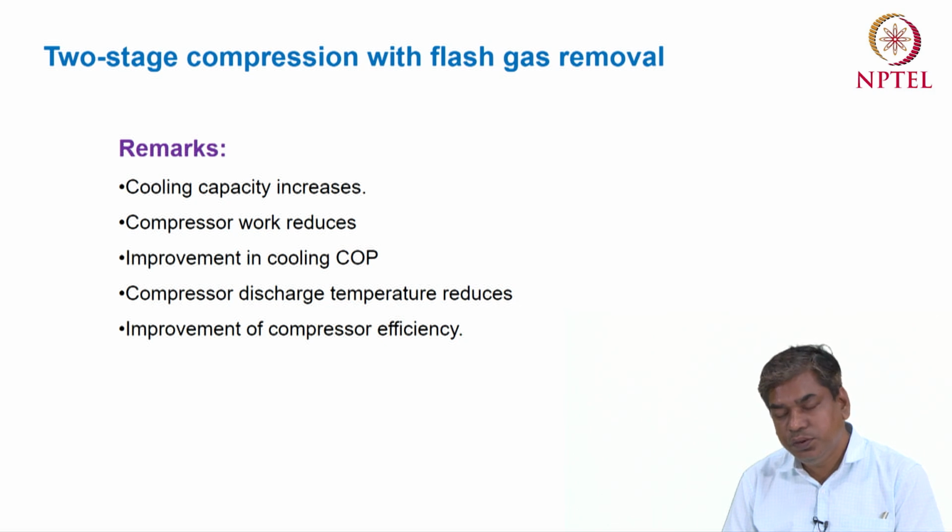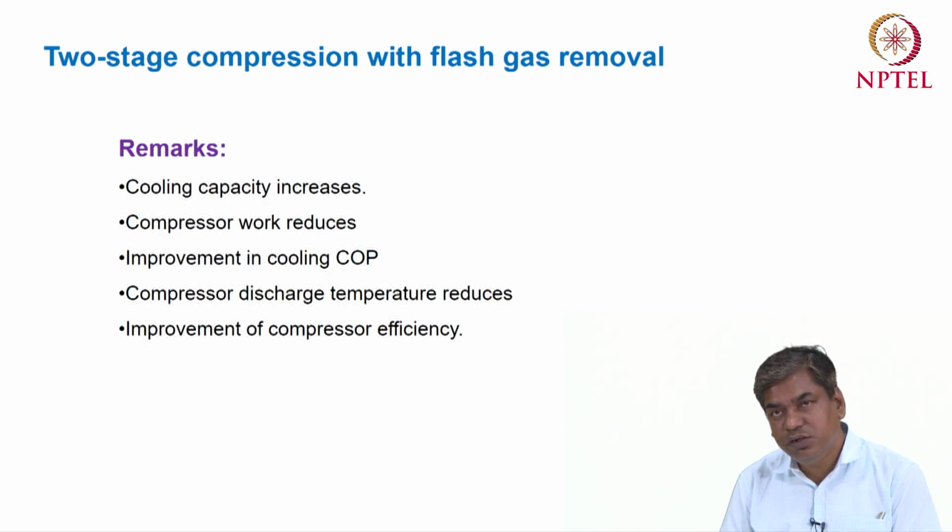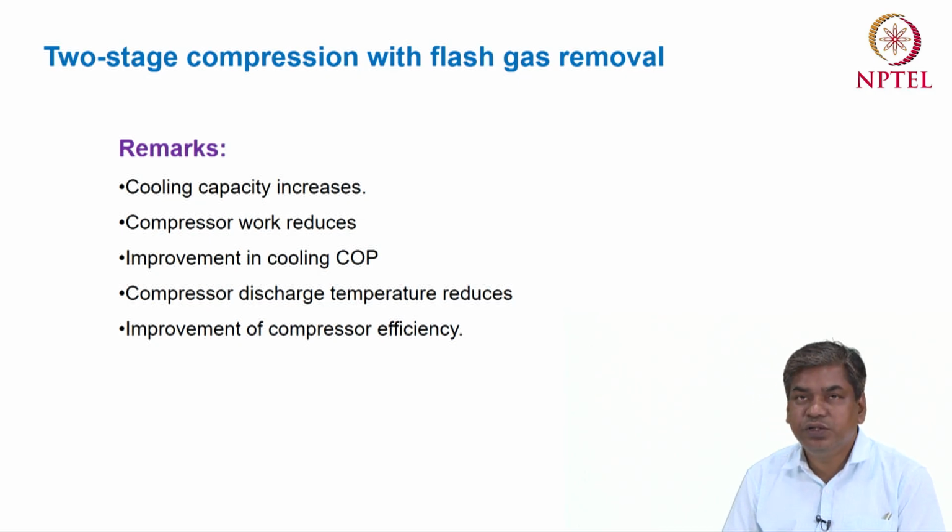If you do numerical calculations for any refrigerant using the two-stage compression with flash gas removal, we will see that the compressor work reduces.